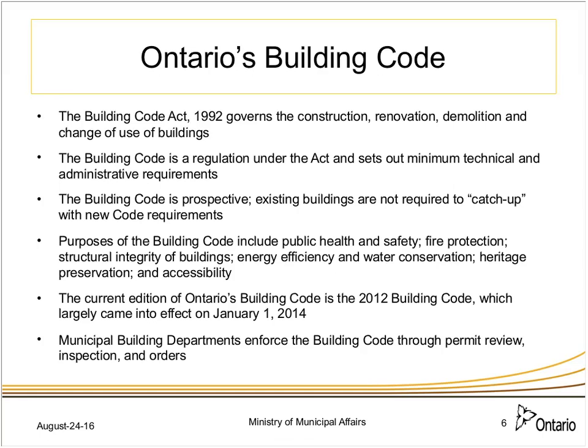That is not the case. The Building Code does not mandate retrofits. We don't make that happen. If you built to a code, you're assumed to continue to meet the code. The only time that you begin to require changes to catch up are when you're doing new work.